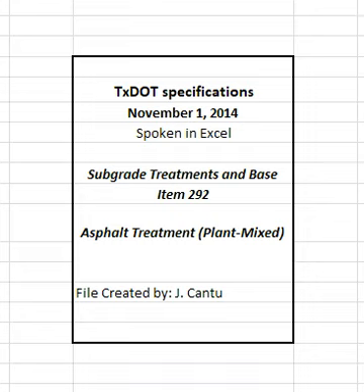Table 3. Gradation requirements for fine aggregate. Sieve size and percent passing by weight or volume. Sieve size 3/8, 100% passing. Sieve size number 8, 70 to 100% passing. Sieve size number 200, 0 to 30% passing.